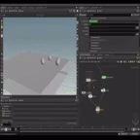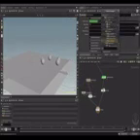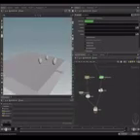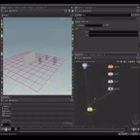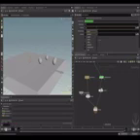To set the static object, we can do it by using this icon here and search for the node. Or another useful way is to write an expression here that will lead us to the path of wherever is connected to the second input, or wherever input we have in this network. This expression is called opinputpath. You have to write, between quotes, opinputpath, open parenthesis.